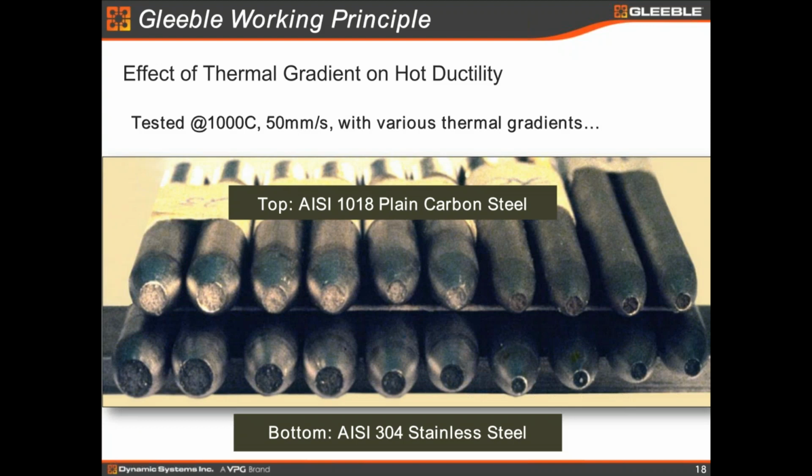If you really don't pay attention to it, you would think, well, if the temperature is the same, the stroke rate is the same, then the ductility and the strength will be the same. But you see, it's different. Why? Because we have a different thermal gradient in the specimen.